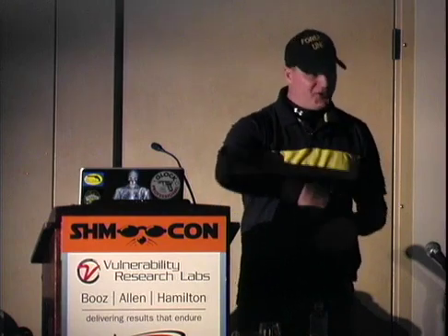And in some instances, like for instance, there's some laptop drives that are like 80 gigs, where the head is stuck to the platter. All you literally have to do is open the drive itself and turn it with a screwdriver without touching or scratching the platters. Turn the platter till it breaks the torque. It's called stiction, basically. We used to have this problem back in the early days when RLLs, MFMs, and stuff like that would actually stick.